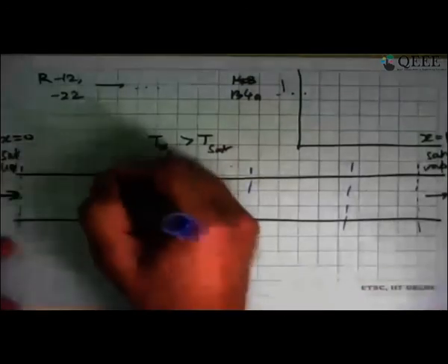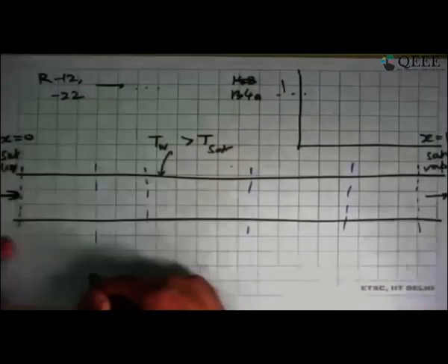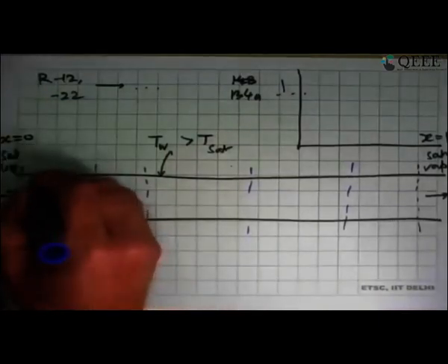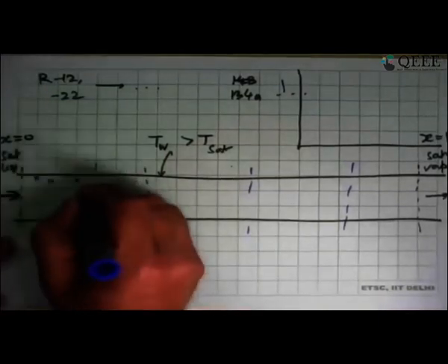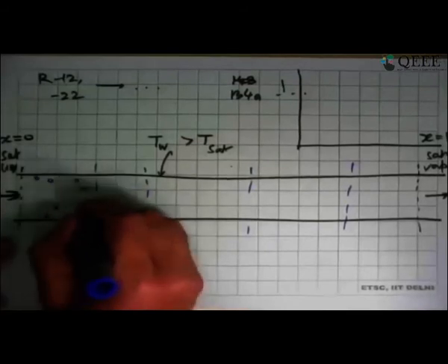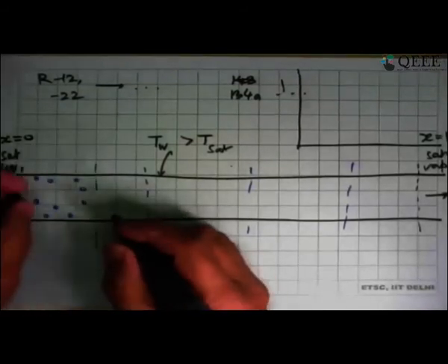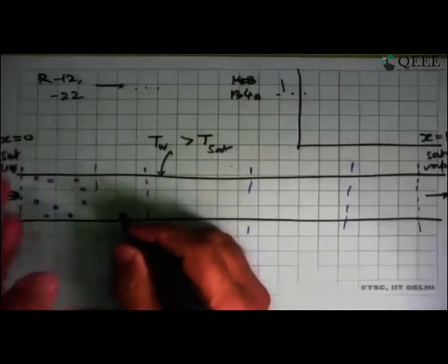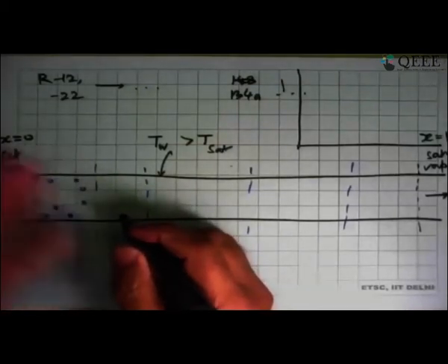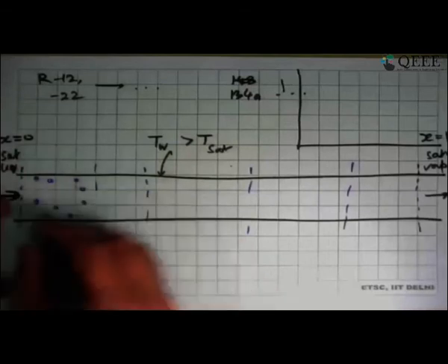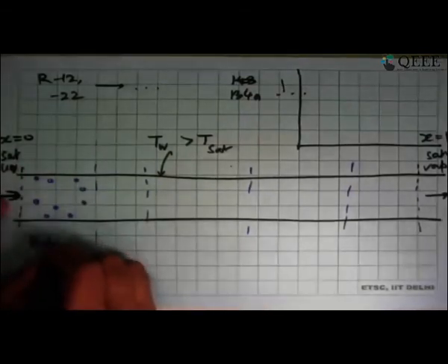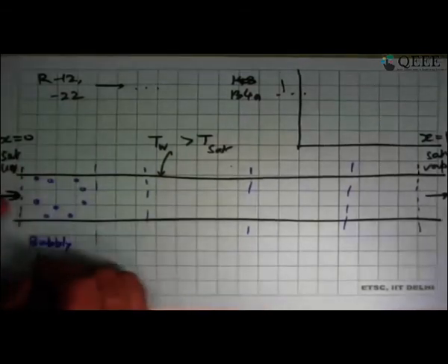In the first part of the flow, because of the heating, we will see nucleate boiling and very small bubbles will come out, which will maybe detach or are pulled back because the fluid is flowing through it, and you will start getting bubbles coming in. But as you go downstream, more and more bubbles are formed, and so you get the first regime here, which is called the bubbly flow.